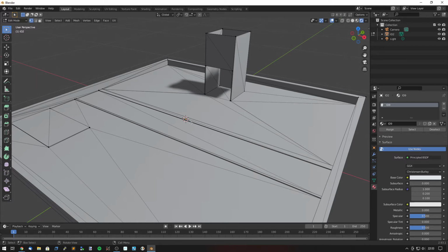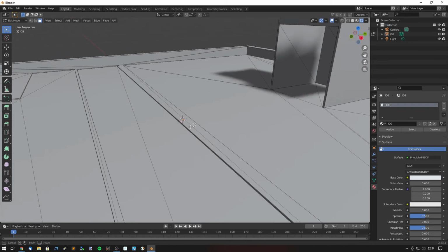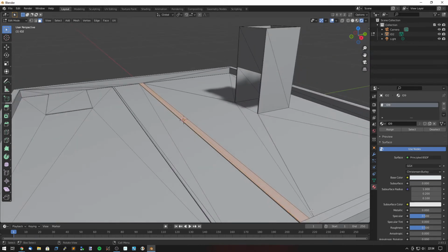Now the easiest way to select these things is to go into this option here, face select. So we have node or vertex select, which will allow us to pick the points, but only the points. And we have the option here to edge select, which allows us to select the lines. But I actually want face select. I've got two faces here, these two, because it's a rectangle with two long thin triangles on it. So I want to say please change that to a new color.